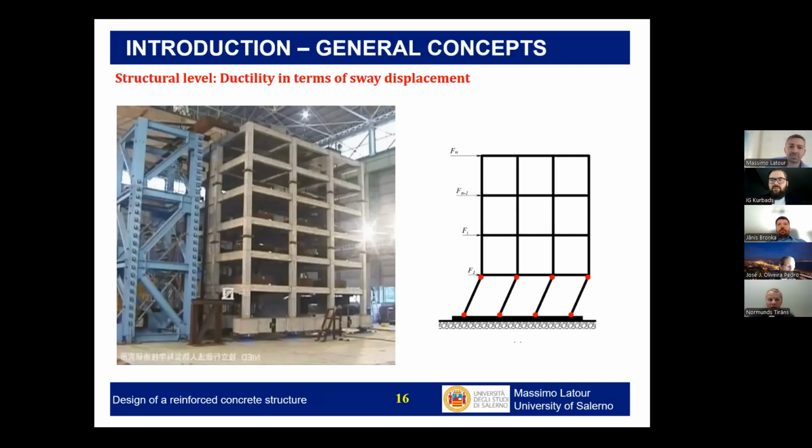Go to the good depth, and execute the foundations at the level that you need to have a controlled and short foundation. So if it's up to 5, 6, 7 meters, I think a direct foundation at the good level should be the best solution. Yes, for sure.